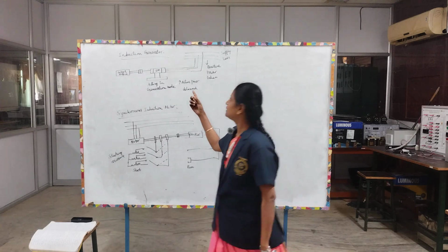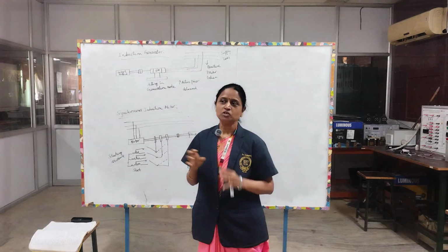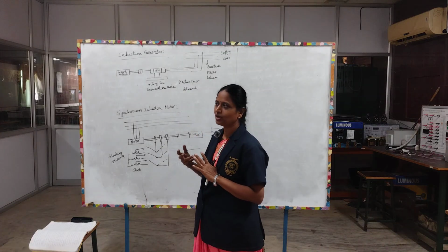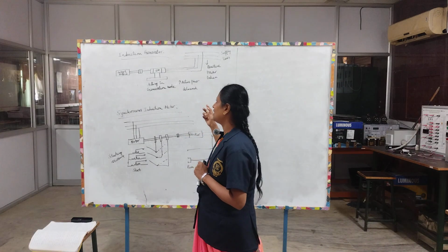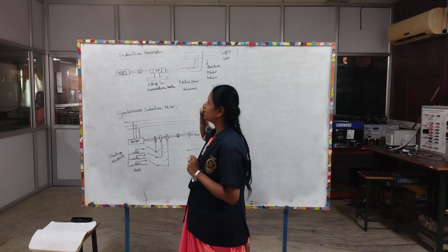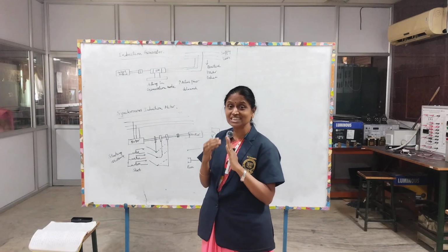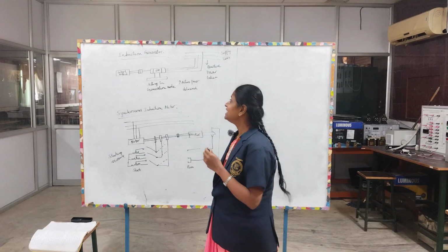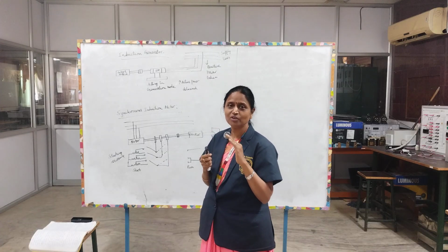So the next topic is induction generator. A generator is nothing but a machine which takes mechanical input and converts it into electrical output. Here we are considering the combination of induction generator. We have studied about induction motor. In a generator, usually the slip will be negative.